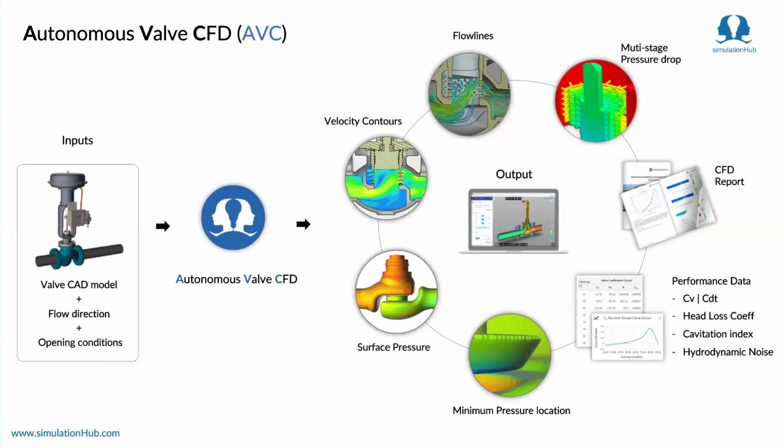The workflow of AVC is pretty straightforward. As a design engineer, or as a valve manufacturer with the design team, they just need a 3D CAD model of their valves: upload the valve, specify the flow directions, specify the openings. And once this is done, AVC will take care of all the conventional CFD steps. It's an autonomous workflow that we have developed. And what we get as an output is